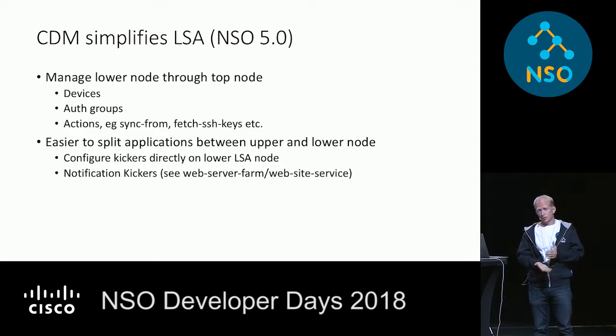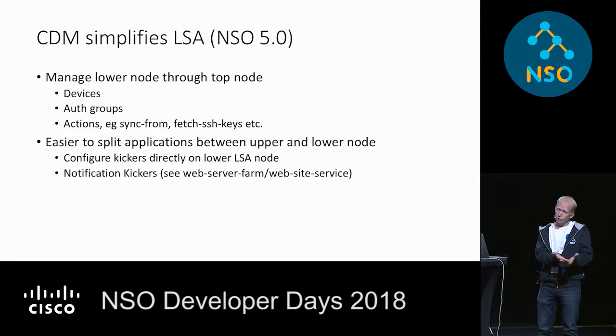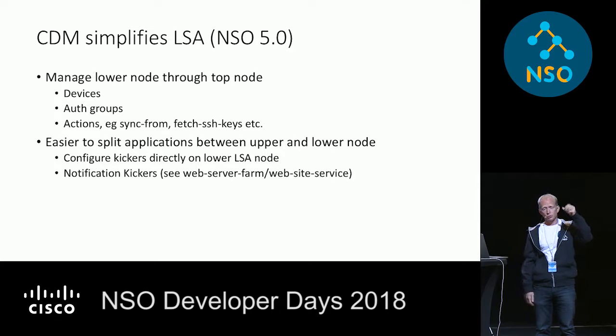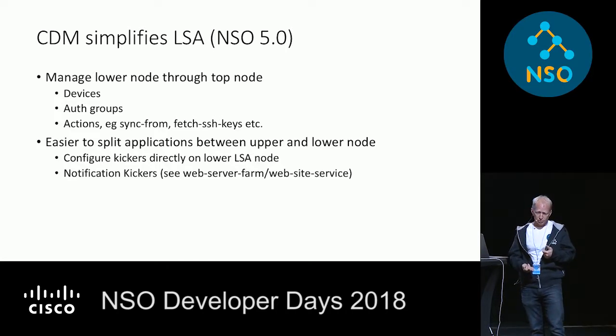And not only that, one issue with using LSA is that it becomes trickier to manage devices. You have to add the device locally on the lower node. So you can't just manage everything from your top node. If in a device cluster you have just one place where you can manage all the devices, you can add them to lower device cluster nodes. But in LSA, the upper layer doesn't really see the devices on the lower node. So I know that some developers wrote their own packages for adding nodes on the lower LSA layers, which is very useful, but it's a bit cumbersome.